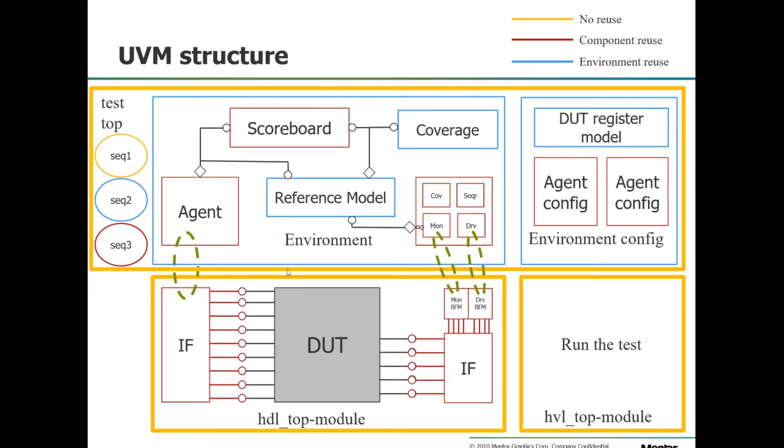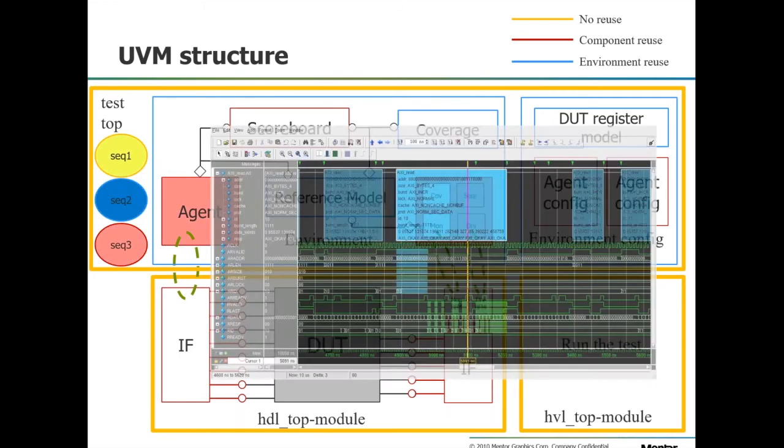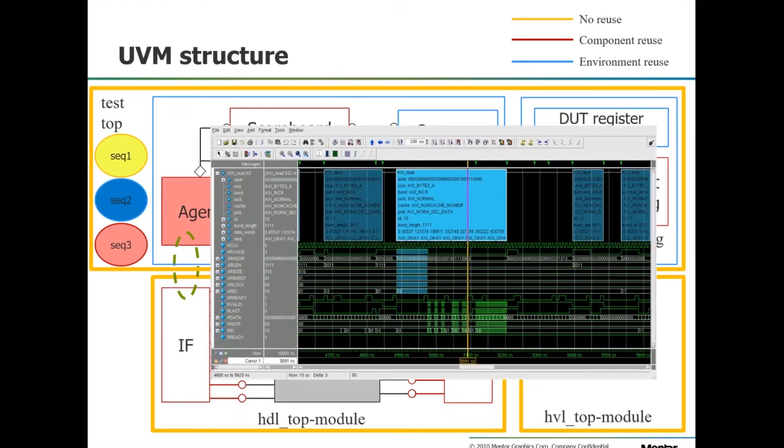So one of the things that UVM is really good at is saying, hey, I want to use this agent in another test bench without needing to make changes. That's all been kind of built in. So it's, as I said, interoperability and reuse. All of the things in the agent take place at what's called the transaction level. So when you're debugging up here in the SystemVerilog world, you're debugging transactions.